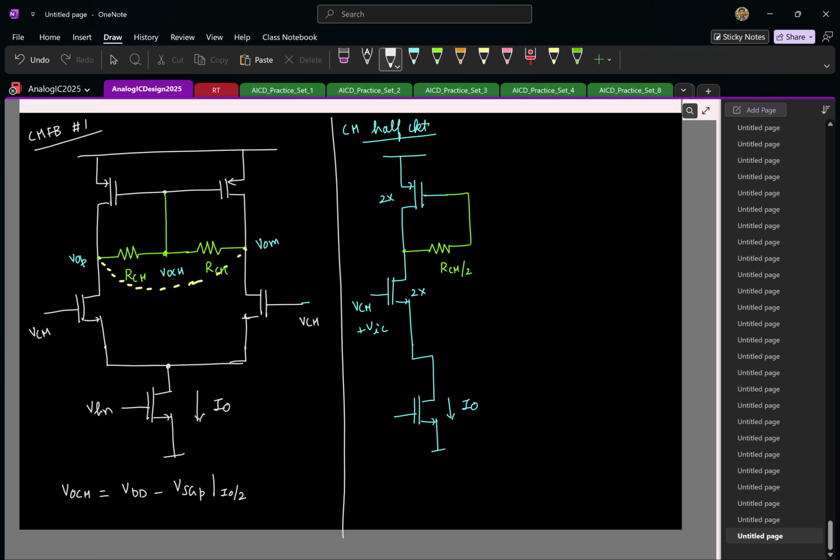Okay. So now at least we know the common mode is getting set to a defined value, not arbitrary. So hopefully the circuit will be biased fine. But remember that our main goal is to not worry about common mode gains. Our main job is to make some block which has a large differential gain, right? This common mode business is a side quest that is required to make sure that the transistors are all biased properly, correct? Now let's actually check if the differential mode picture is fine.